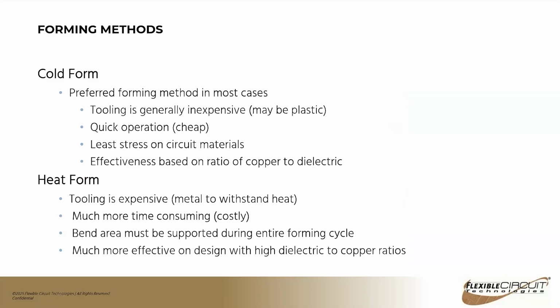Heat forming tooling can be expensive, so typically you'll have to create a die or a set of tools to actually hold the part, put the part inside, which we'll see in some coming slides, heat the part, cool it, and take it out. So there's not just the tooling that's involved, but the time that's involved. We're getting ovens involved and so on.